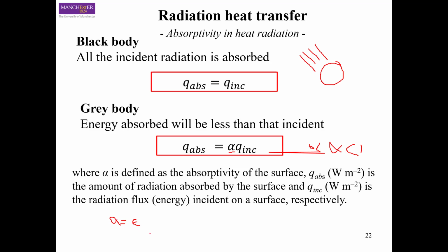Okay, and what it means is that a perfect absorber is also a perfect emitter. So we can only use this relation, known as Kirchhoff's law, in the case where alpha is equal to epsilon, and that is only possible if the two objects have the same temperature and if they are emitting and receiving the light at the same wavelength.